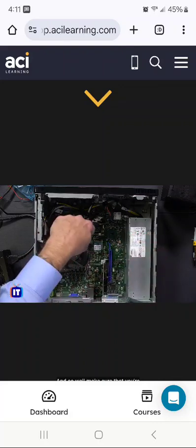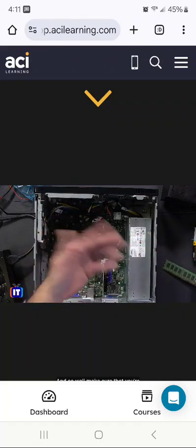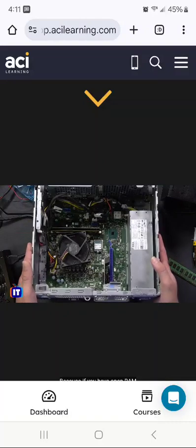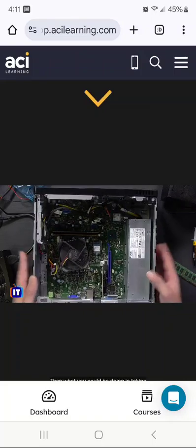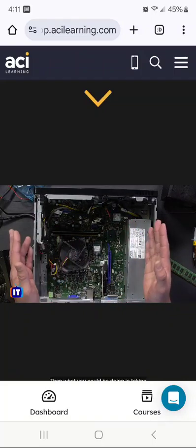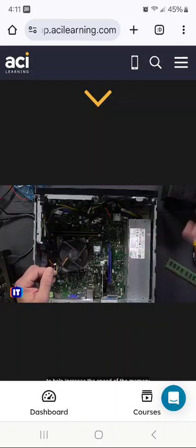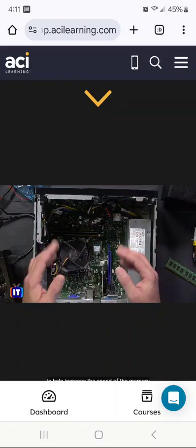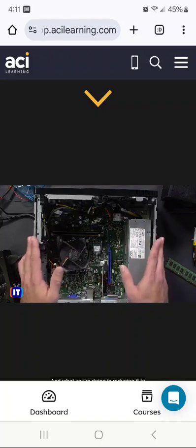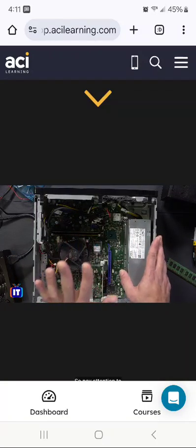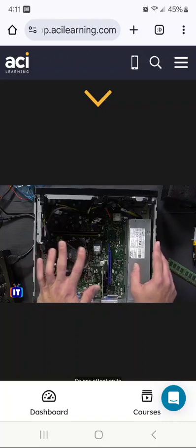And as well, make sure that you're installing them in the right order in the case, because if you have open RAM slots on the motherboard and you don't install them in the appropriate order, then what you could be doing is taking multi-channel architecture that is there to help increase the speed of the memory and the CPU, the performance, I should say, and reducing it to a single channel memory architecture, and that's not what we want. So pay attention to the memory matching as well.